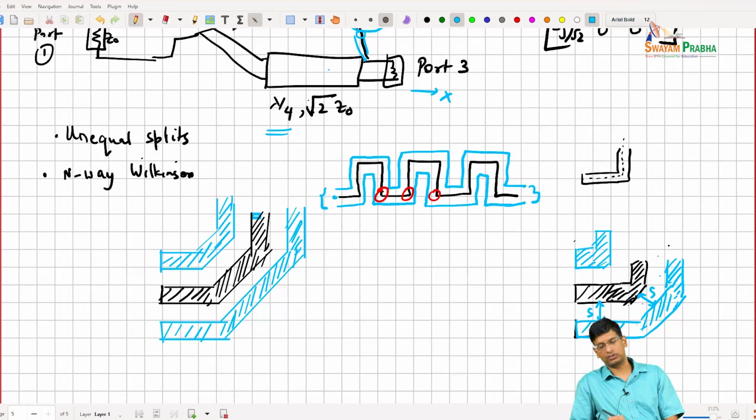This approach generally works pretty well to get these kinds of meanders. It depends upon the area that you're willing to spend, but EM simulators will of course capture it. We have seen similar approaches work pretty reasonably at the lower millimeter wave frequencies.